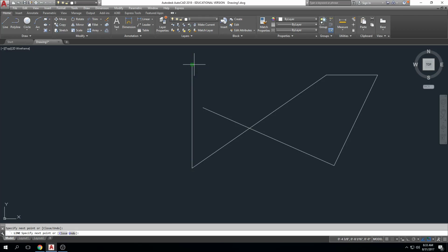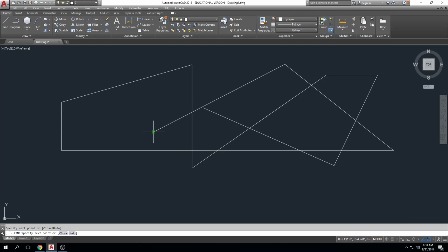These lines, the line command, it's a continuous command. So when we click, it starts itself over again. It says, hey, continue on, right? Because it assumes that you want to draw more lines in sequence. So essentially it's chaining itself. It's a chained command, all right? So as we draw these lines, we chain, and we're clicking away and drawing lines, okay?